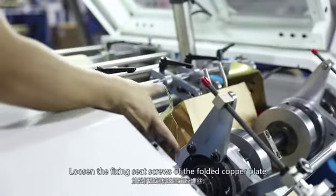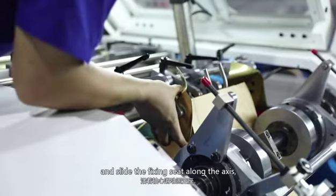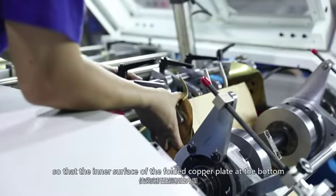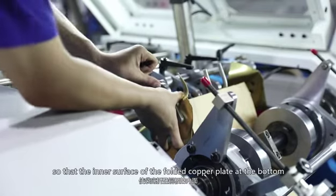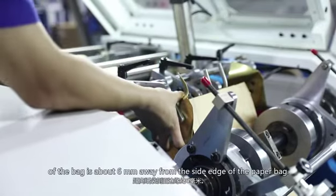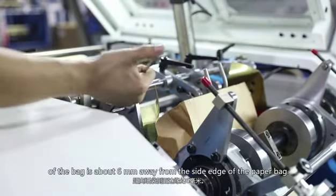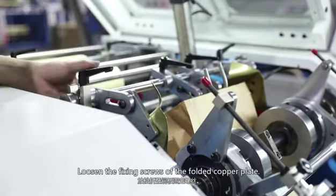Loosen the fixing seat screws of the folded copper plate and slide the fixing seat along the axis so that the inner surface of the folded copper plate at the bottom of the bag is about 6 mm away from the side edge of the paper bag. Loosen the fixing screws of the folded copper plate.